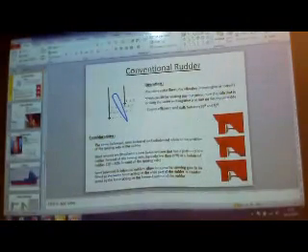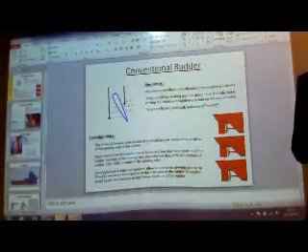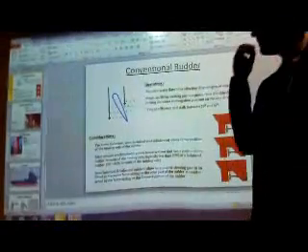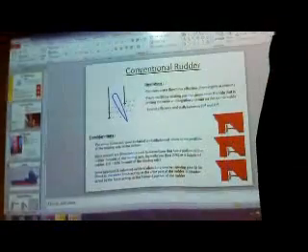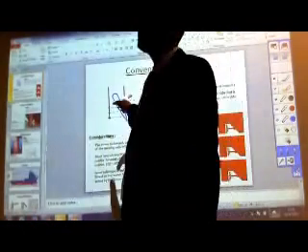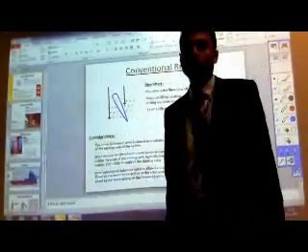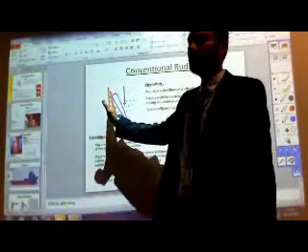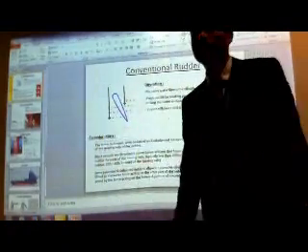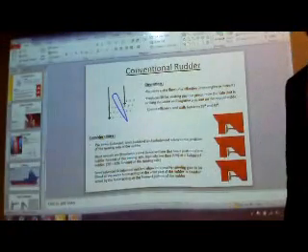Now we are talking about the steering system. So this is a basic conventional rudder. When you move a rudder about in this kind of situation, it is going to cause two things. One is it is going to cause drag, and the other is it is going to cause lift. When you move this from the main normal streamline, it is going to create lift. Lift is the direction that it is going to try to push the vessel, and drag is because of the resistance to flow that it is causing. Okay?